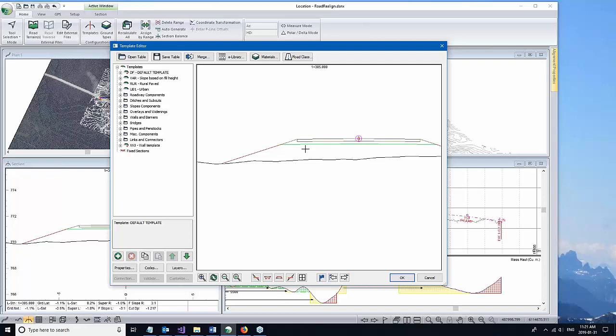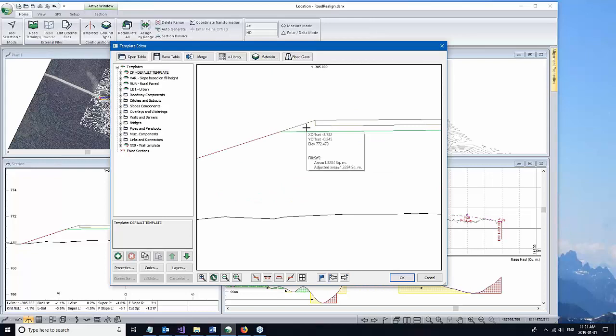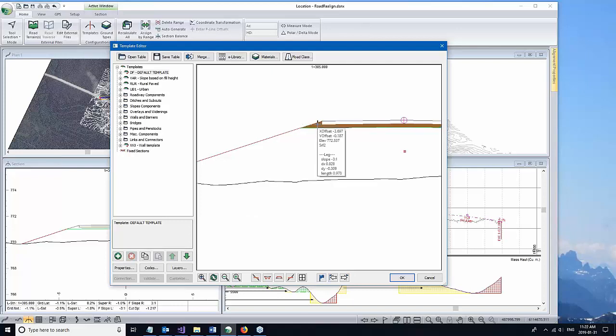So that subgrade line, the materials above it are tracked, and you can actually tell what they are by putting your cursor in here. See, it says SRF2. Put my cursor in here, it says SRF3. You can shade those areas. I shade that, so that's my SRF2.